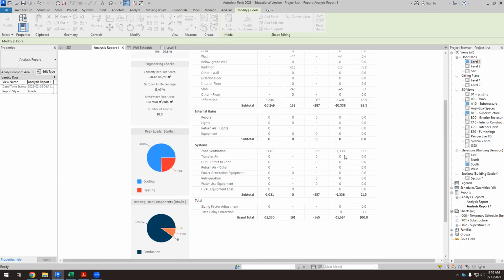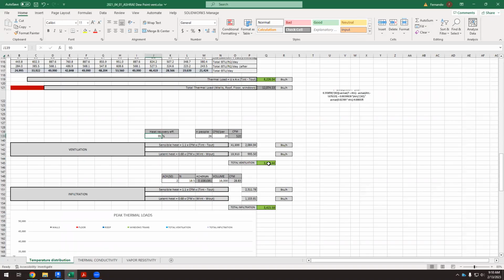Okay, so the total ventilation load is 16, 24, 25,000. So the heat recovery, if this has to be 25,000, the heat recovery can be 70%, 65%. Yeah, so that makes sense. Around 60%. Okay, so that makes much more sense. So here we have considered a 60% heat recovery, which is, yep. Is there a way to make that? It's not standard.